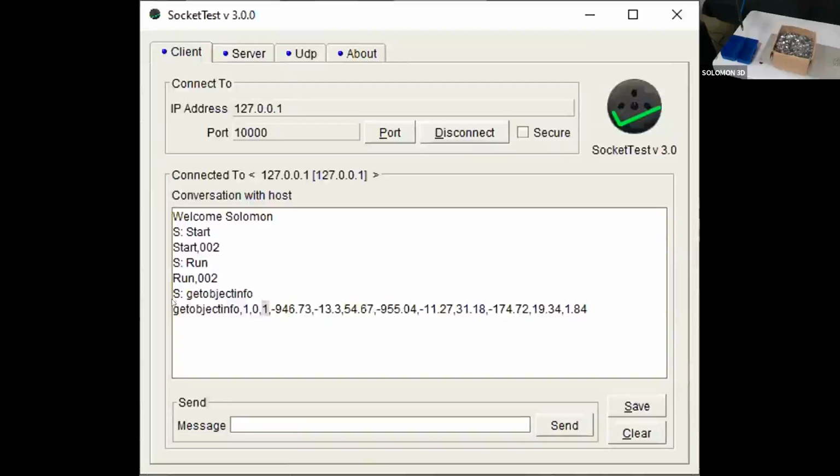So using this string, you can use the robot language to parse through the string and extract the pick coordinates and set up some variable positions inside your robot mission as your pre-target and target coordinates. The process for using a PLC is extremely similar, except that instead of sending it as a string, it's just updated into some PLC registers, and you can input those coordinates into the robot as variable positions as well. So this way, we don't need to connect the robot to AccuPick at all. You can handle all the robot missions yourself. You basically just send commands to AccuPick and check their statuses, and we just provide you the pick coordinates.